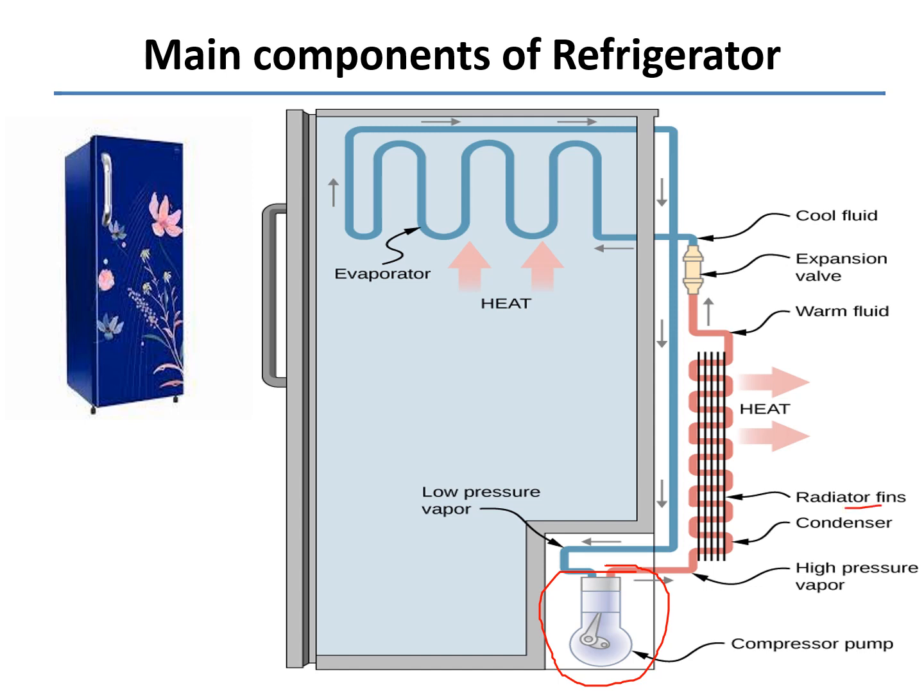The next is the condenser. If you see the back side of the fridge, you see these coils. These coils are the condenser, and fins are also attached to increase its heat transfer area, to increase the amount of heat dissipated to the surroundings. The third component is the expansion valve, and generally in the refrigerator a capillary tube is used as the expansion valve. And the fourth main component is the evaporator, which is actually the cooling coil, which extracts the heat of the inside cabin to get the cooling effect.